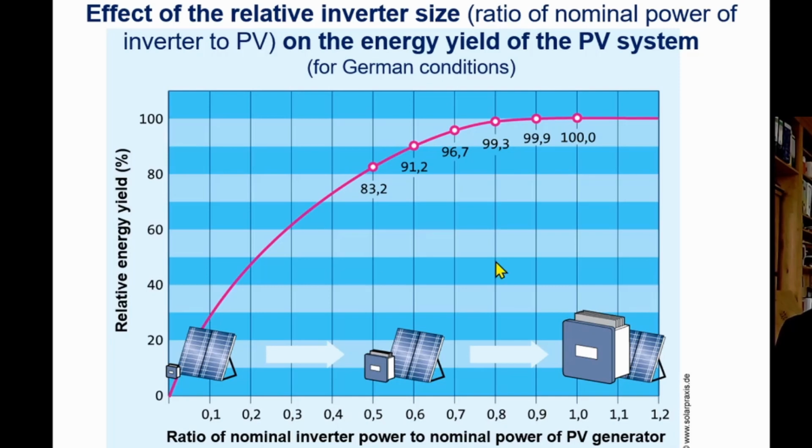For example, if you buy only an 800 kilowatt inverter, you will lose some power. It occurs seldom, but sometimes you have very high irradiance levels. Also, you have to consider the performance ratio because you lose according to the high irradiance level. You will also have a high operating temperature, and this will reduce your actual output. So the actual loss is very little.